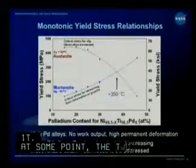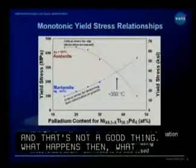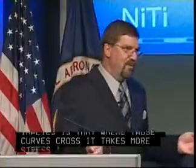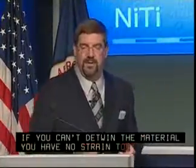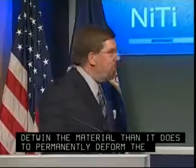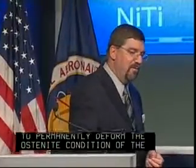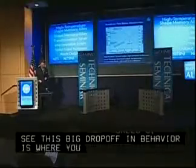What that implies is that where those curves cross, it takes more stress to detwin the material. And if you can't detwin the material, you have no strain to recover back. So it takes more stress to detwin the material than it does to permanently deform the austenite condition of the material. So right around 350 degrees C, where you see this big drop off in behavior, is where you get this crossing of the two plots.